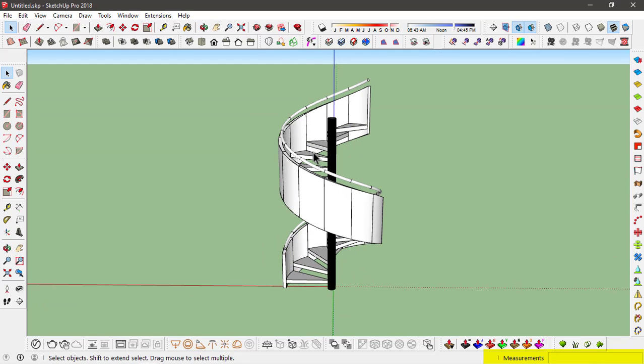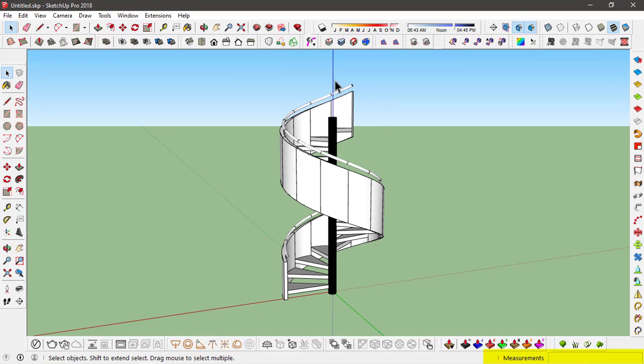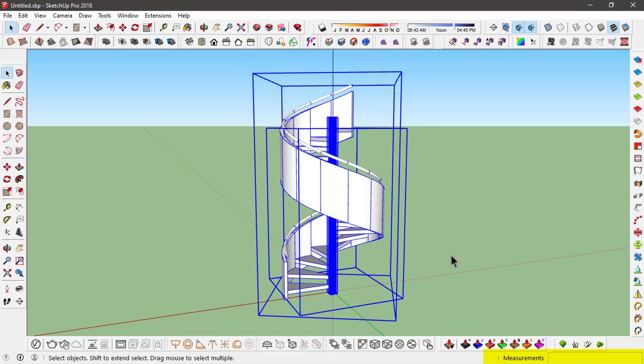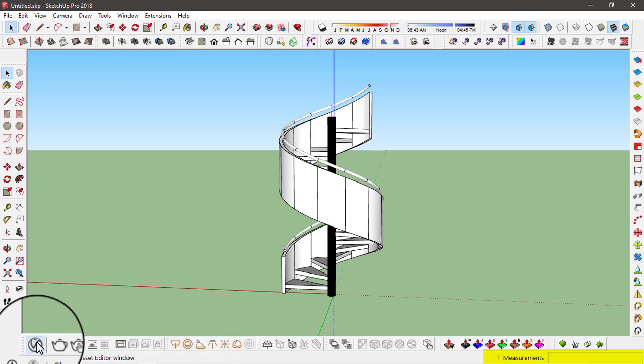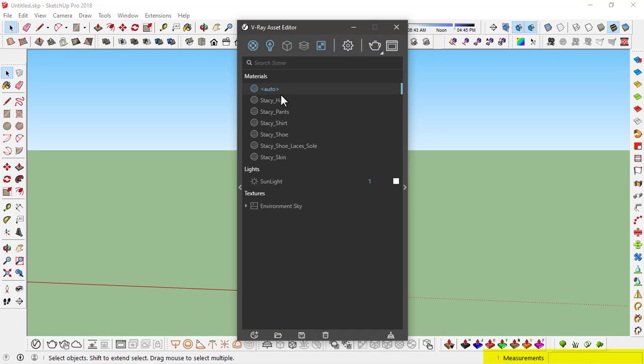To begin the rendering process by V-Ray, what I'll do basically add some colors or textures to these objects. So go and click on V-Ray options, and first of all I'm going to delete all these default materials that are already there. So select them and hit delete. Now that we have no more default materials in this file, we can add on our own materials.